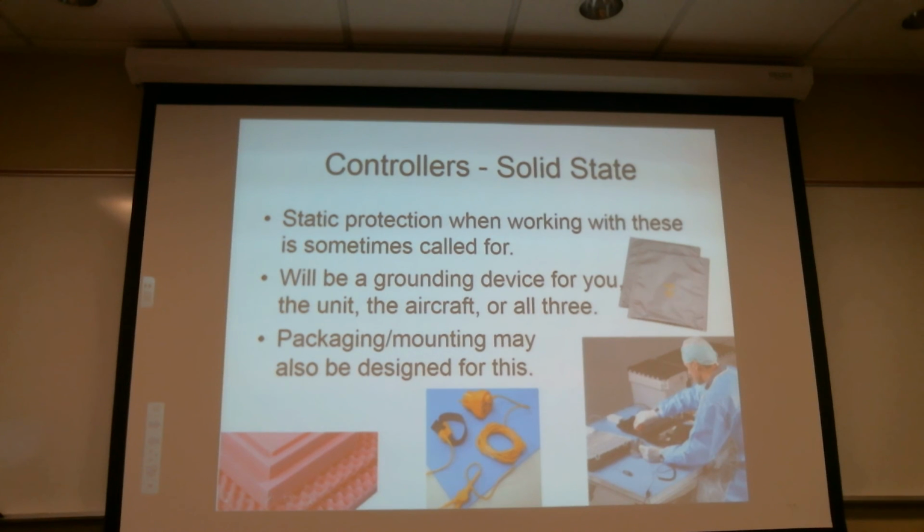There's standards around it. For example, the little network plug that you've got in there for hooking up to a network inside of your computer, it's a little modular thing. There's like 7 little wires in there. You may not know this, but if you take a USB plug, you can fairly snugly shove it right in there. Don't ask me how I know. Of course, the USB plug wasn't designed to go in there. And that outer metal housing is going to lay up against all 7 of those pins and just connect them real nicely to each other. The truth is, nothing will happen. Because the standard for any network output device, any network connector, is you can short anything to anything and it won't damage the computer. Okay?